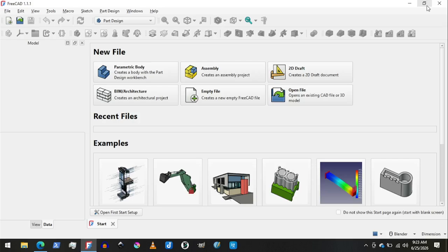Now, parametric design is a little bit slower, but it is easier in the long run for bigger projects, because you're telling the computer to build relationships between different parts of the design. So if you decide I want this to be twice as big, if you've done your parametric design correctly, you could even do it in a way where you have a scale factor and you just say 2, and it doubles all of the measurements.